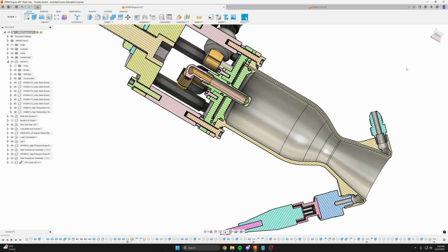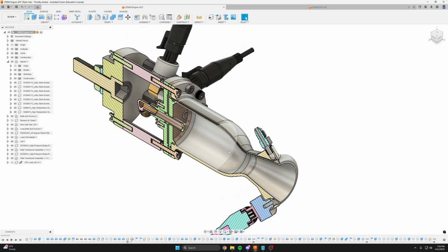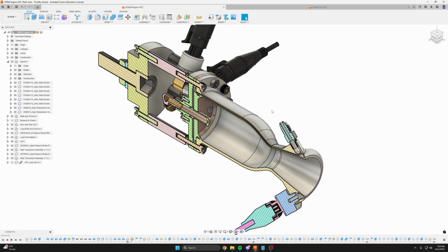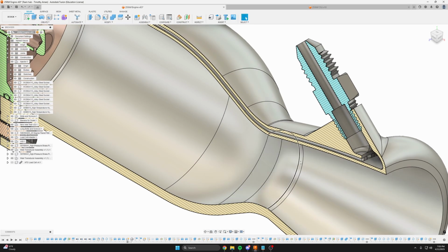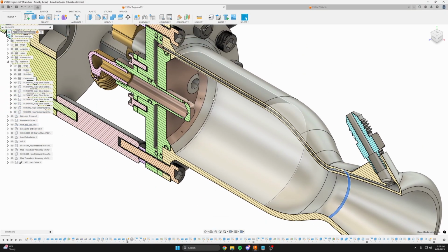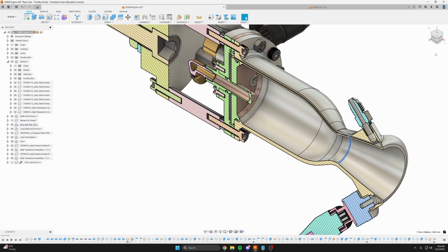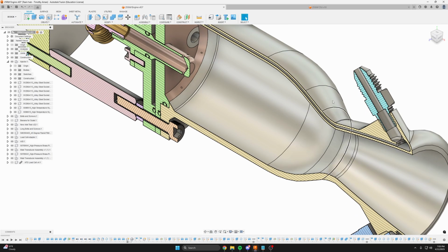I chose to use the yield tensile strength for the hoop stress calculations. You look at how it changes with temperature, and then you look at the worst temperature that's predicted in the chamber, at the throat. Look at the material properties, do the hoop stress calculation, and then see what your margin is, and that will sort of drive the temperature limits.